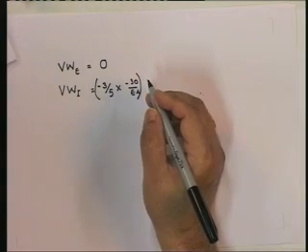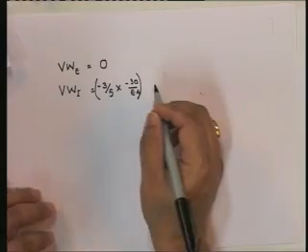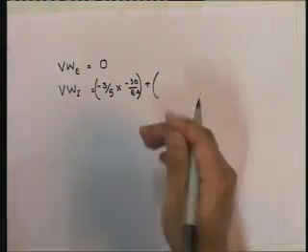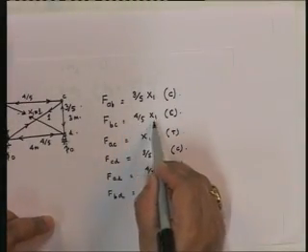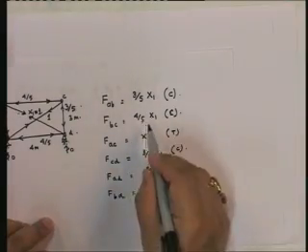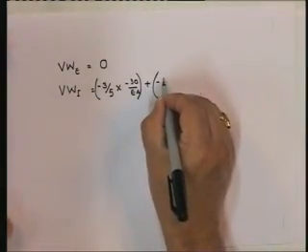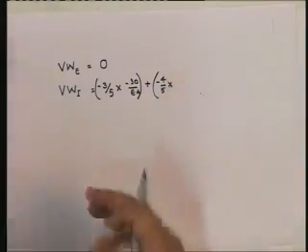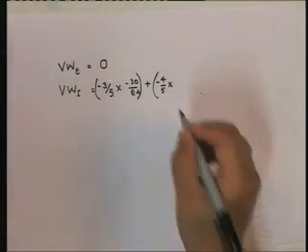Now let's go from AB to the next member. The next member is BC. So let us look at BC. What is the virtual force in BC? The virtual force in BC is 4 by 5 compressive. If we put a unit force, it's going to be 4 by 5. So that's going to be compressive, minus 4 by 5 multiplied by the real displacement, which is minus 40 upon EA.